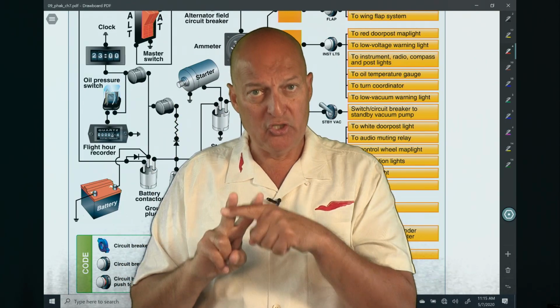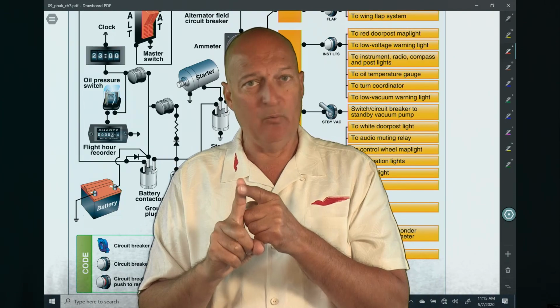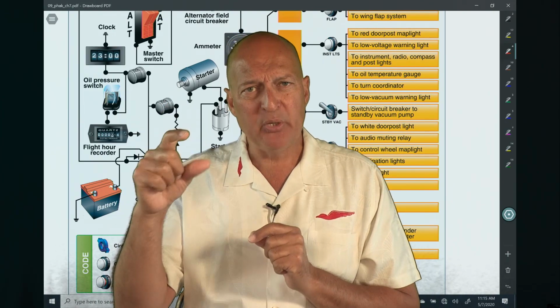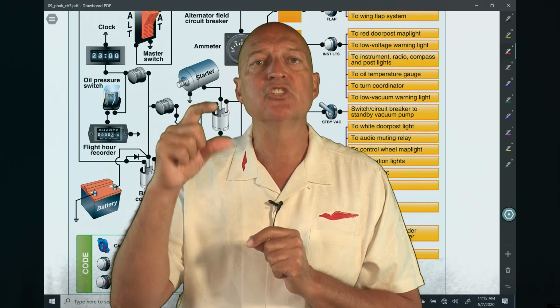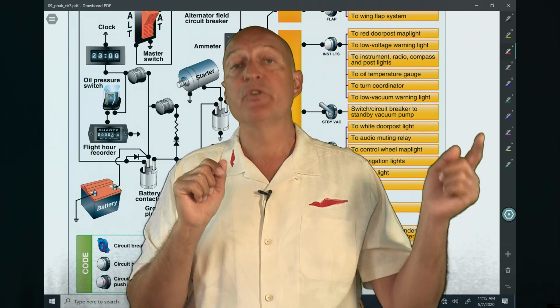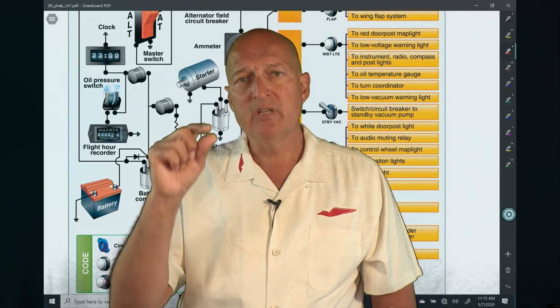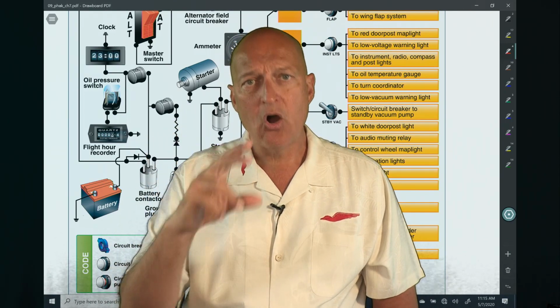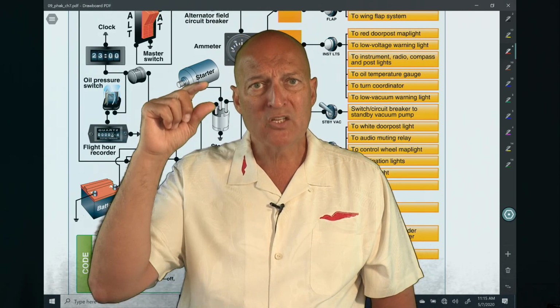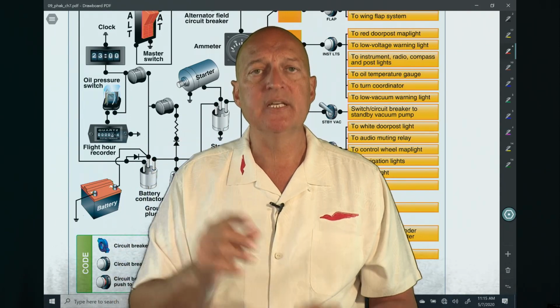I don't need 2 navigation systems, I can make it with just 1. And it starts putting all of those essential items just on one circuit. So with just the flip of a switch, or perhaps 2, you can then relieve the draw on your electrical system to just the essential items.